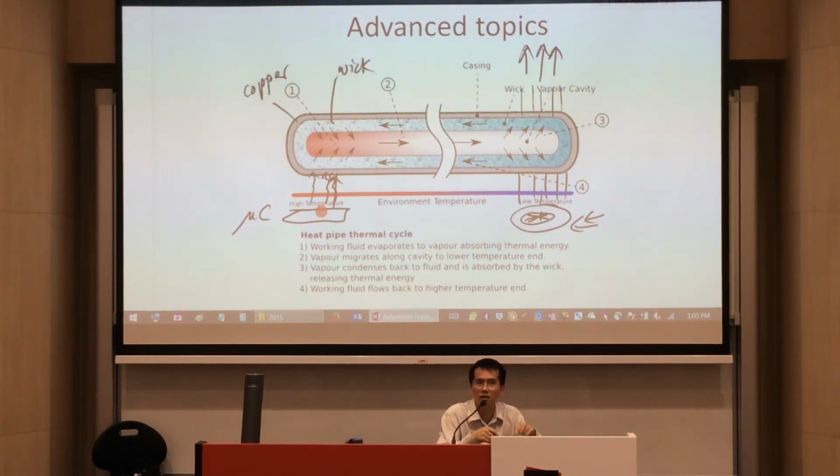And this heat pipe is a revolutionary invention for a small form factor just like your laptop. That's why we can cool down this microprocessor in the laptop in a very tight space, and we can route this heat pipe to another location at the side of your laptop, and then you have the forced convection to cool it down using ambient air.